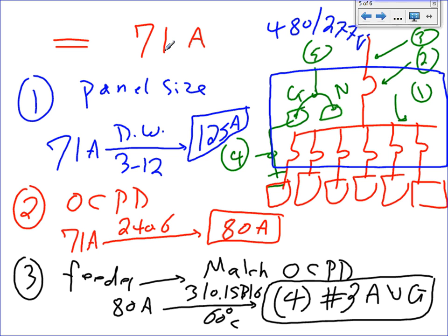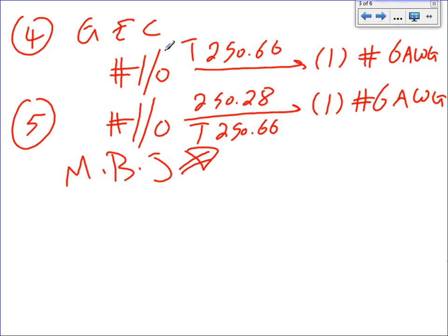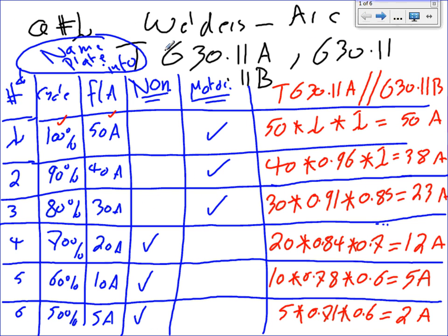For this, I'm gonna pick one welder. I'm gonna do it first from the first example that I did, guys. I'm going to pick the first one, that 50 amp welder. Do you guys remember that 50 amp welder? I'm going to go size a branch circuit for it. 50 amp welder. What was the cycle? 100%. Yep. So okay, everybody's with me. I'm going to multiply it. Okay, overcurrent protection device for conductors.